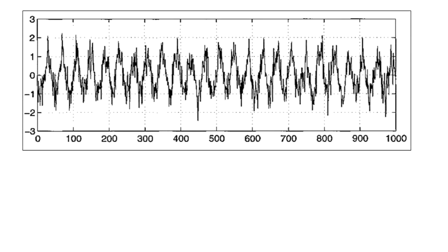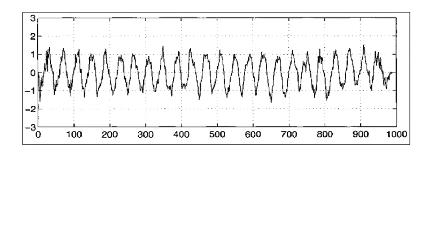So let us see the noisy process, that is the input to the system. It is denoted x of n, the addition of d of n with v1 of n here. So this is the noisy signal here, and the corresponding output of the adaptive filter making use of the normalized LMS algorithm, LMS standing for the least mean square algorithm, having the normalized step size, for example 0.25, and the reference signal obtained by delaying x of n by n0 equal to 25 samples here. So here it is the illustration, and you see a clear improvement as compared to the earlier representation here.